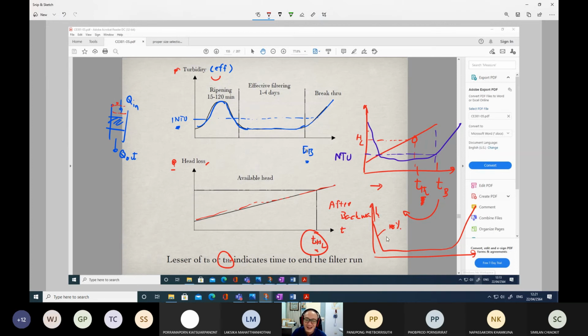Okay, a normal backwash would take approximately 30 minutes for cleaning. So we put the water in the opposite direction. We do it for approximately 30 minutes. And if we do only 15 minutes, what will happen? Some of the materials are not removed, so it's not 100% clean. If it's not 100% clean and you use it again, it will not be a problem.